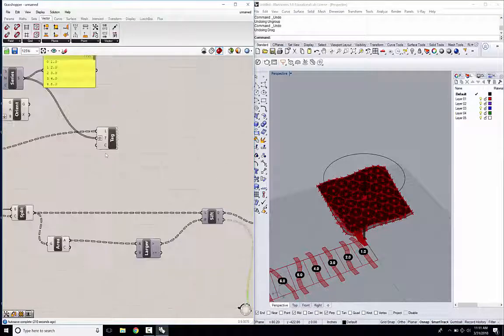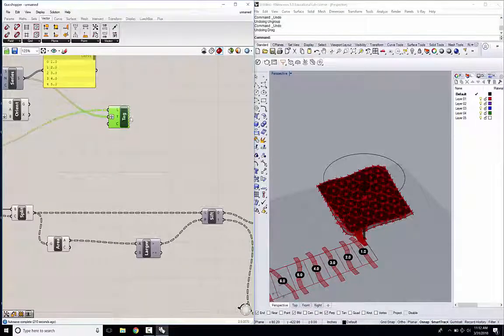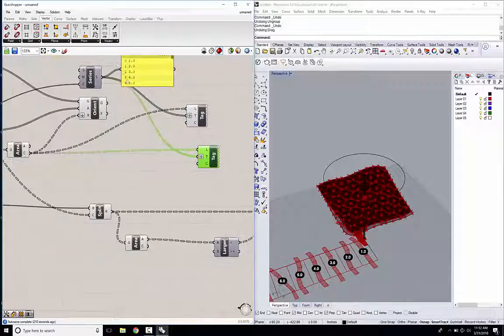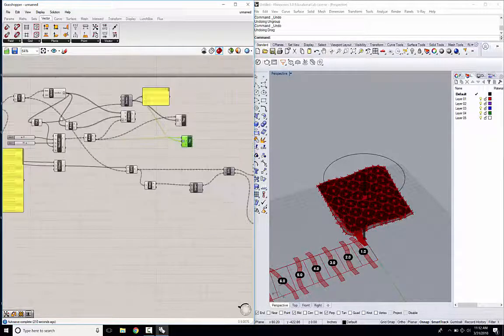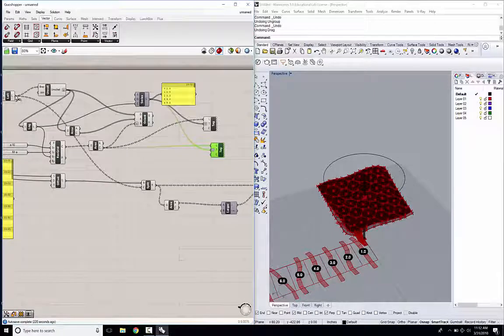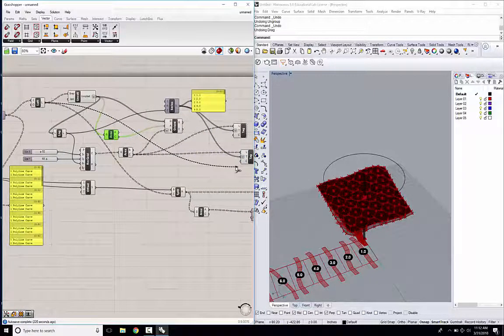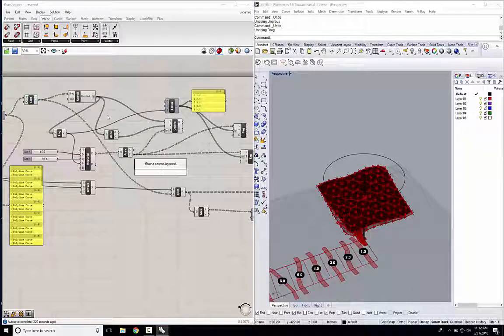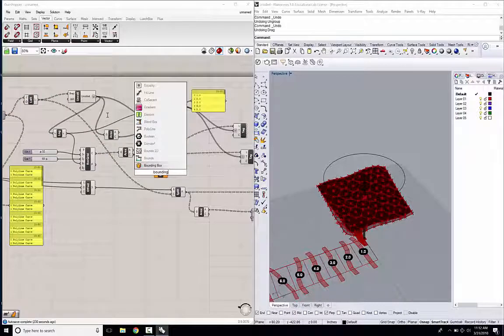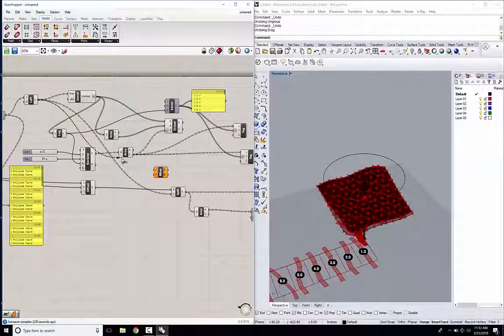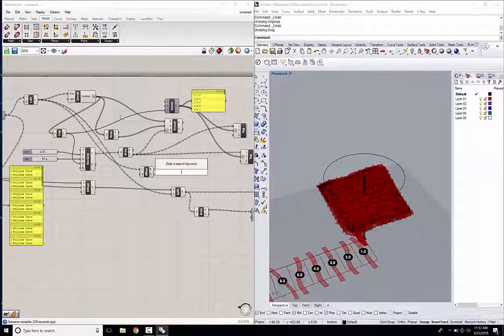So the last component of this, again, is to tag the other hexes. So I'm just going to copy paste this hex tag, and we're going to put it onto the filtered loft components. I'm going to put a bounding box on these guys and a volume component, which gives me another centroid.